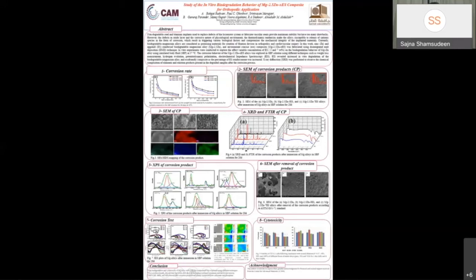The electrochemical impedance spectroscopy showed that the 3 eggshell composition has the highest corrosion resistance, as shown in figure 7. And in figure 8, the localized scanning vibrating electrode technique was done to assess the details of the microscale corrosion evolution, which confirmed that 3 eggshell is the optimum concentration to resist corrosion. The cytotoxicity was evaluated in mouse embryonic fibroblast cells, indicating the composition containing 3 eggshell is non-toxic, as shown in figure 9.